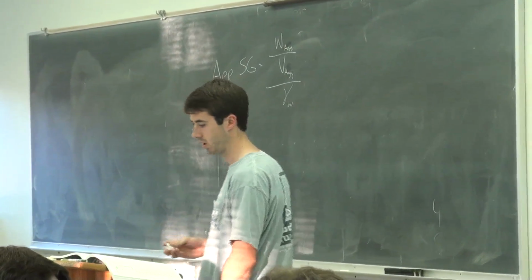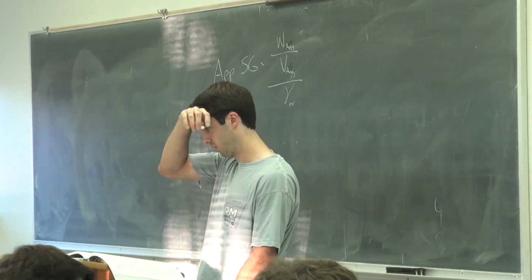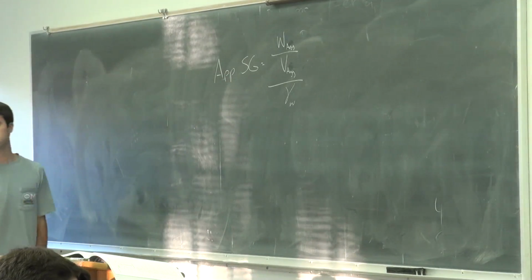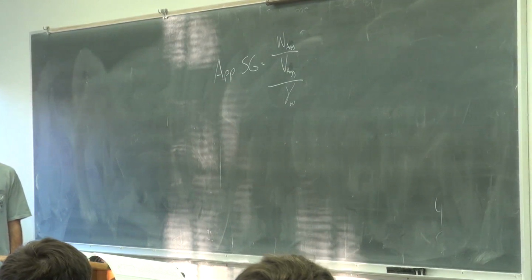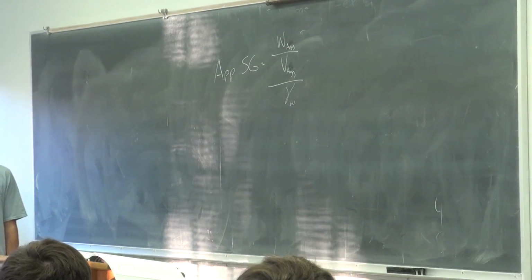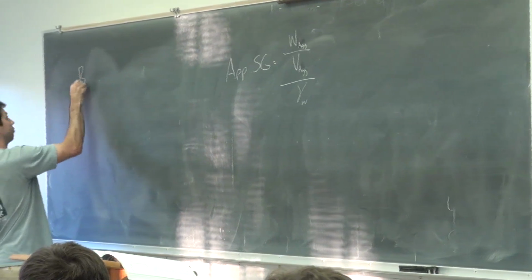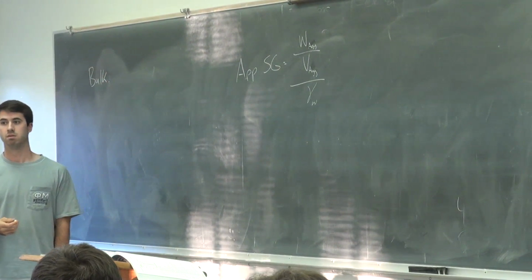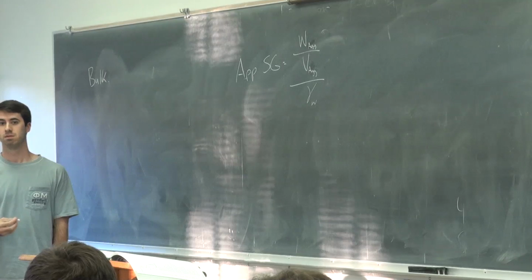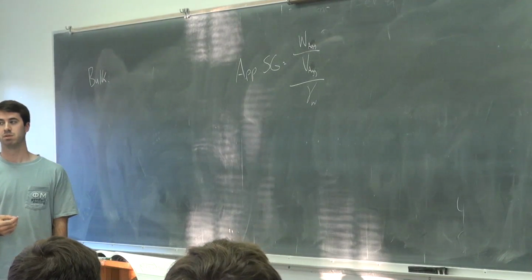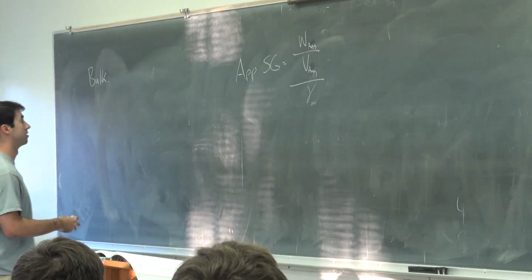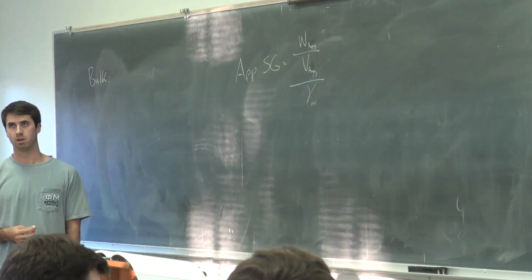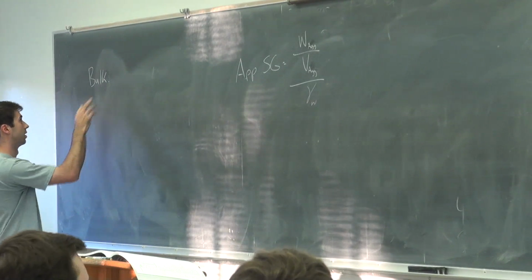So you're literally looking at just what the specific gravity of the rock substance is itself. Does that make sense? Then if you go to bulk, you've got two different types. And those are, anybody? Oven dry and saturated surface dry, SSD. So you've got bulk. By definition, what does bulk mean? What's now added in? Voids? Voids are never calculated in specific gravity calculations. At least not in these.